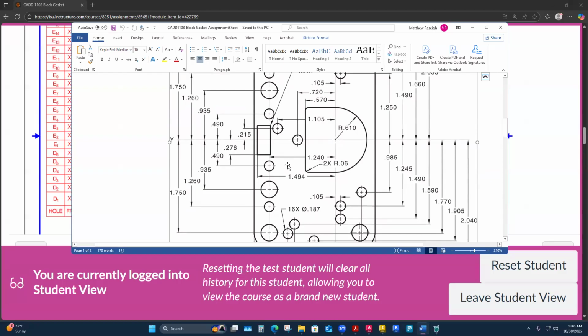That's a good point, I have that dimension, but it wasn't clear. It's such a small difference, and they don't drag these center lines through to each other to see if they are slightly offset. But by the nature of how far it looks like it's off the corner, the center line for the circles should have all been the same. And I think I built my table that way. So if you've already built these holes at this dimension, I would leave them. It's okay.